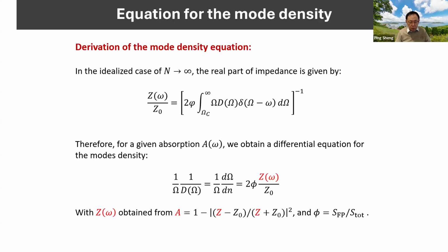And this adjustable Z can be related directly to A. And A here, we can use the optimal absorption spectrum that we derived earlier from the noise spectrum or the target spectrum we want to absorb. So in other words, Z here can be directly related to the target sound spectrum we want to absorb, okay?